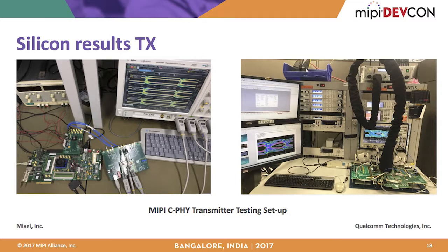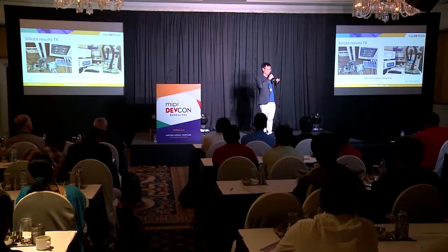On the TX side, it's easy to test. You are just monitoring what is coming out of the silicon. So basically, it has some RTB board, termination board, and some setup here, and you can see the waveform from the device. Again, all the logical part is common to both CSI and DSI. We use DSI-1 or DSI-2, and CSI-1 and 2, as the protocol layer. The only difference is the physical side, so physical side test is the most important thing.